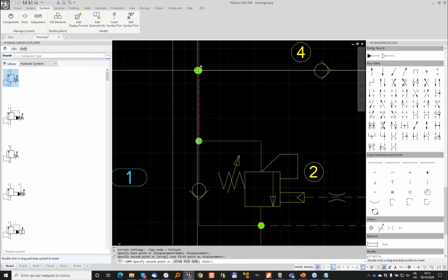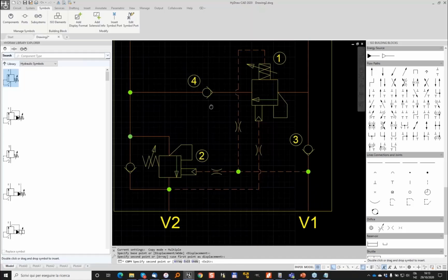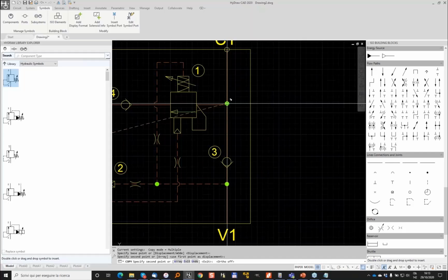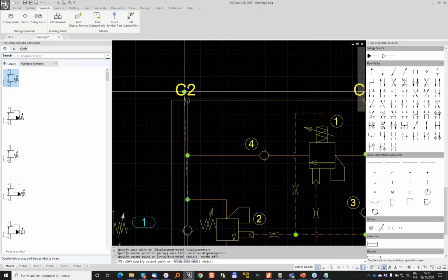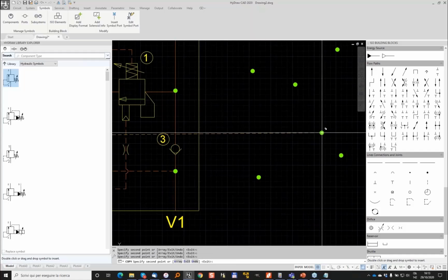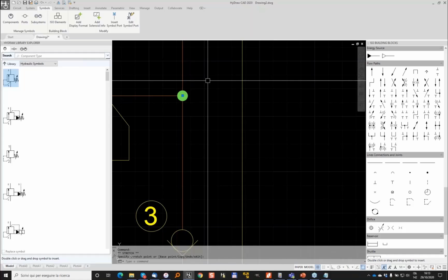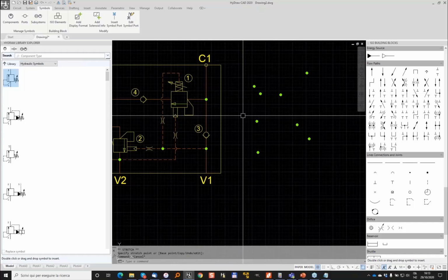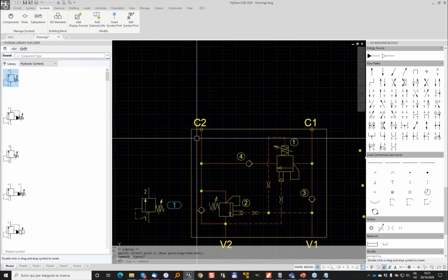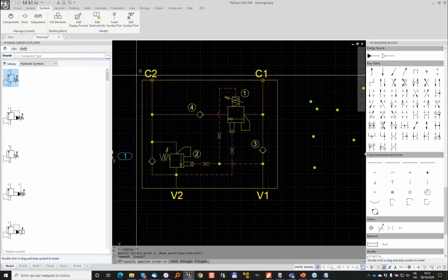So in this case, you have full control and you can keep copying all the entities where you need. So you can keep adding all the dots where you need. Instead of copy and paste, that will leave the connection where you leave the paste command, in this case you have precise control of the position of the port of the copied entity.